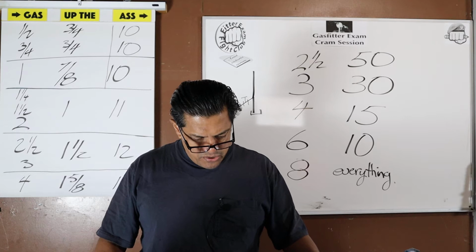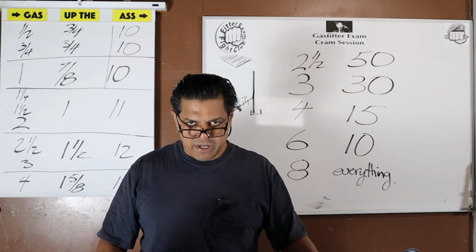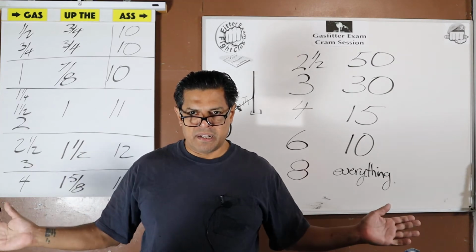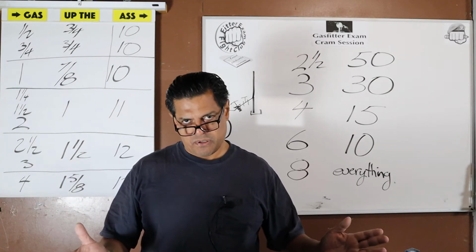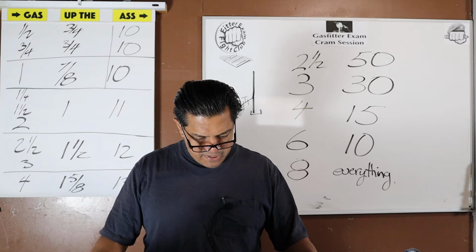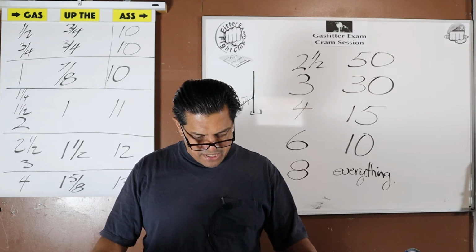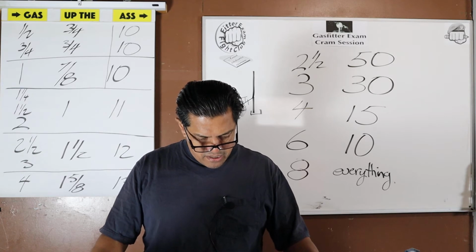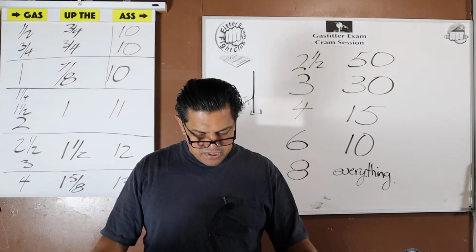Question 9. Used pipe, fittings, valve. Already I'm thinking, they said the word used, so no, not allowed, period. But let's finish reading the question, right? Used pipe, fittings, valves, and other materials must not be used in the gas piping system except where they are free of. That sounds like you're trying to trick me. D, you can't fool me. Material cannot be used under any condition.